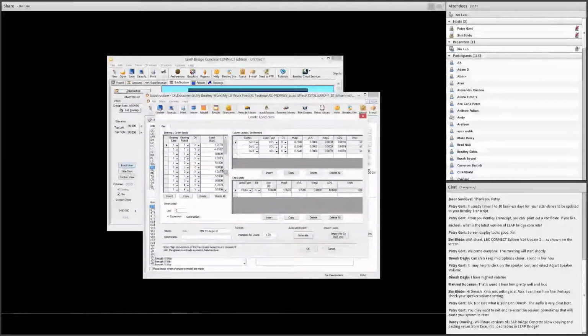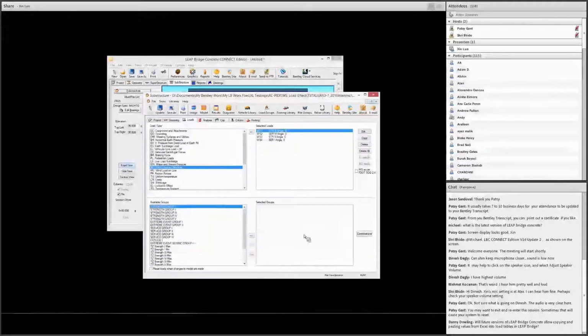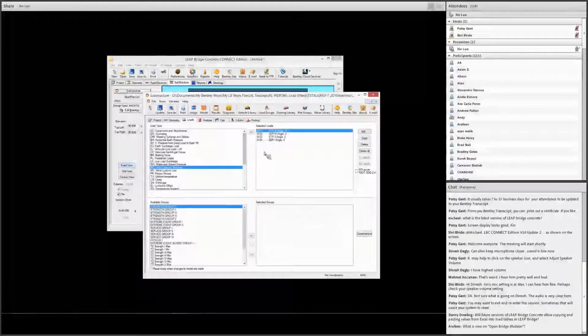This portion shows the wind load at the bearing locations. And this shows the wind load in the column, and this shows the wind load in the cap. We click. So you can see here for the one wind attacking angle, 0 degree, we will generate the 4 different wind load cases for 4 different limit states.